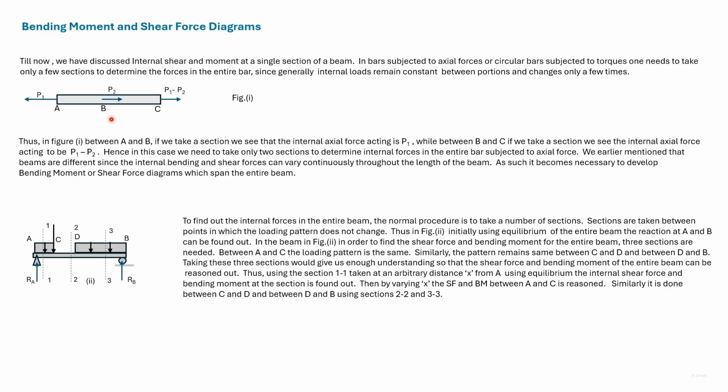If we take a perpendicular section between B and C, then we will find that the internal force is P1 minus P2. Bending moment and shear force are also internal forces in beams, but they often vary continuously throughout the beam.